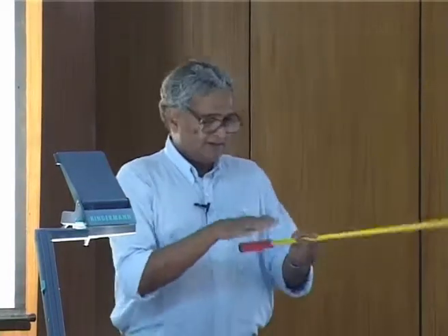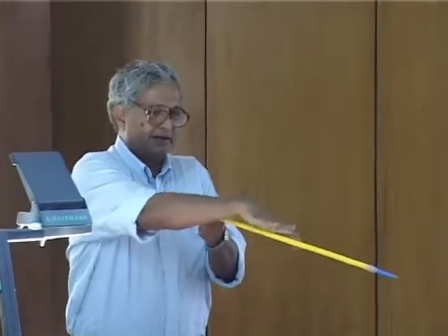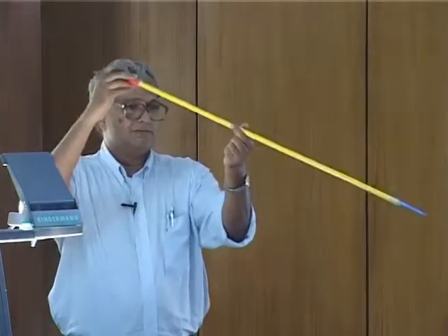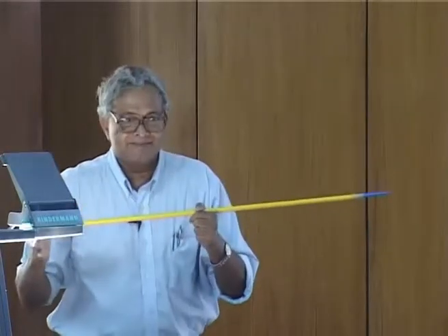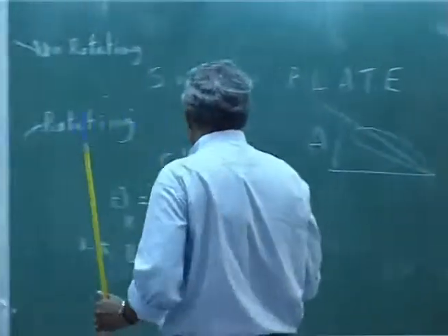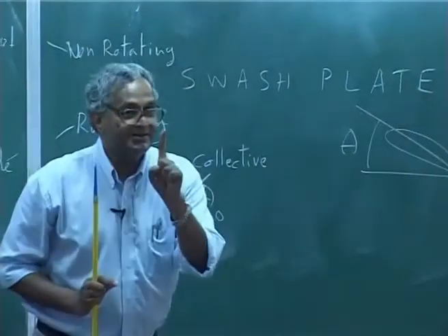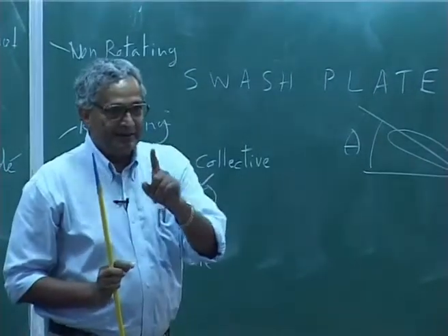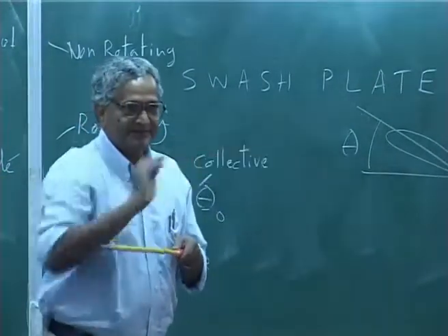Now, if you tilt in these two planes independently, which means by suitable adjustment I can tilt along any axis, you follow, because if I can tilt about this axis and about this axis, that means I can suitably combine them and go in any fashion. So, that is called cyclic pitch input, and it varies once in a revolution depending on where the blade is.